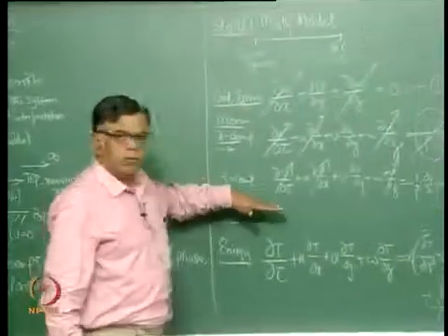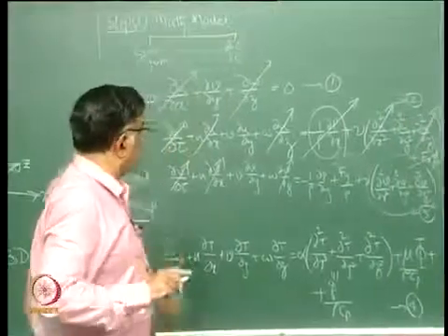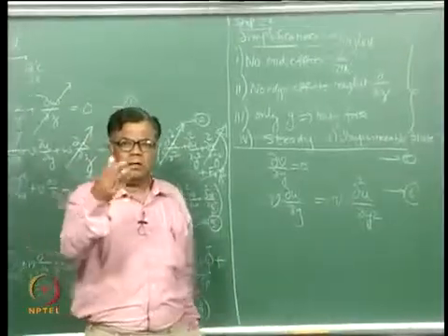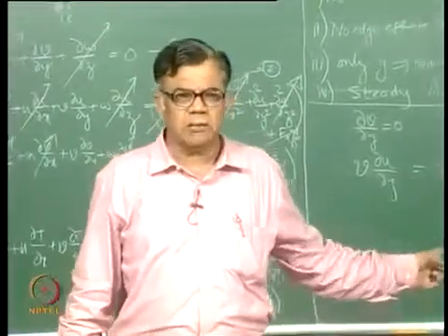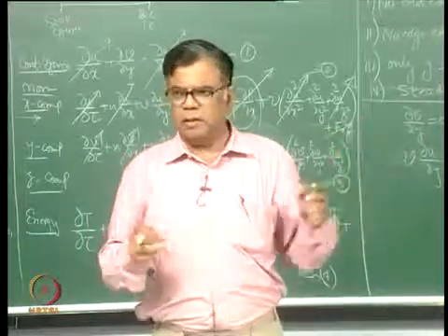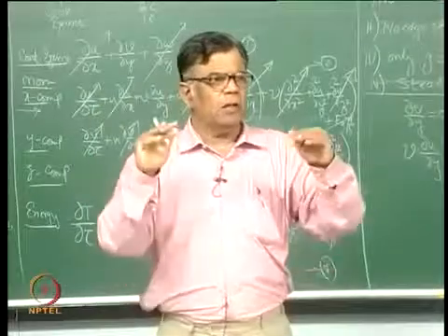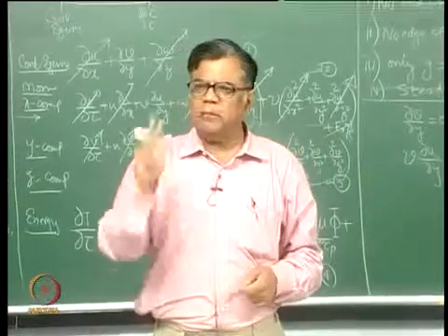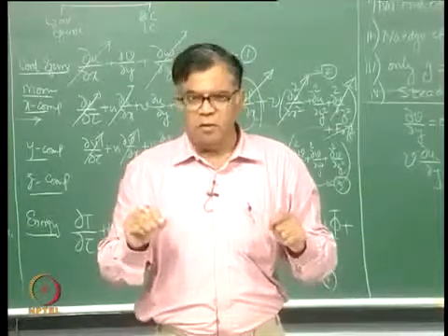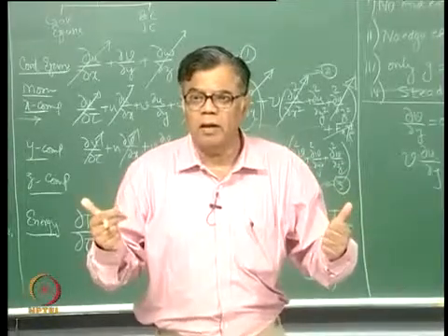Now take V equal to 0 at the wall, both walls. Take the continuity equation you have written, del V by del Y equal to 0. So what is the consequence of this? If you apply the boundary conditions on V, what is the consequence? V equal to 0 at the bottom plate, Y equal to 0, and at Y equal to L also V equal to 0, dV by dy equal to 0. Therefore, what is the conclusion? V equal to 0 where? Everywhere.